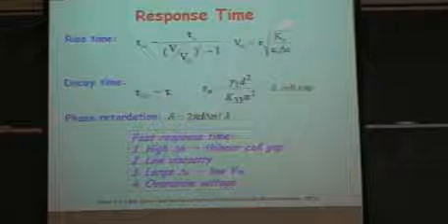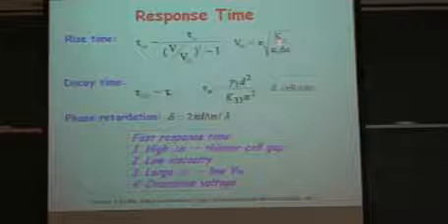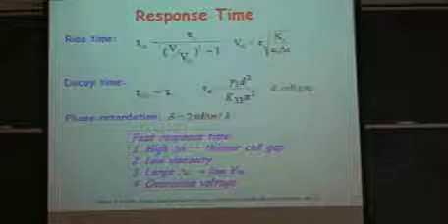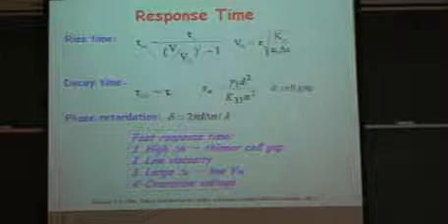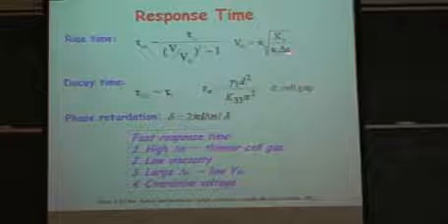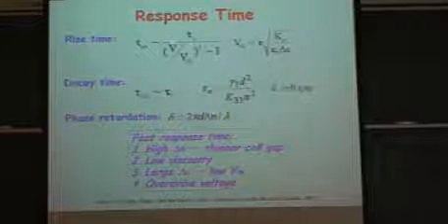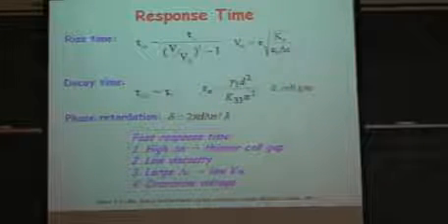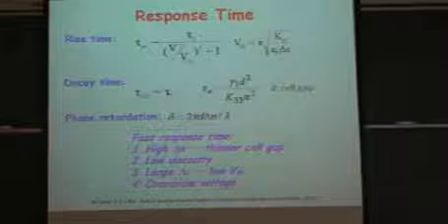This one is for the voltage, because the liquid crystal starts to rotate after the threshold voltage. So this is the elastic constant, and this is the dielectric anisotropy. So with high voltage, the rise time can be improved by applying voltage.